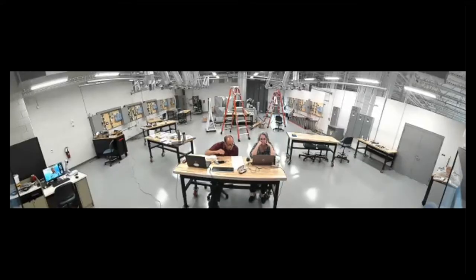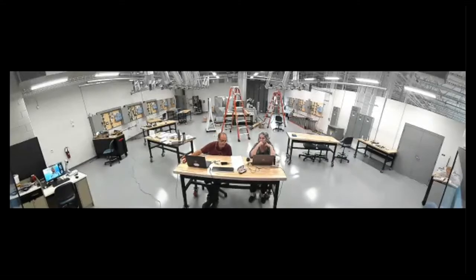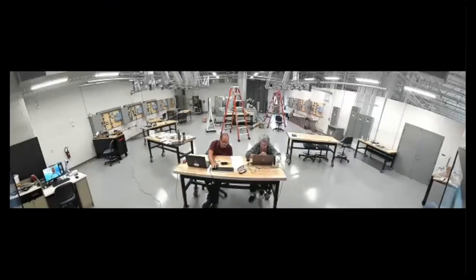Anybody have any questions on that? A little question, I should have asked it yesterday, but in this software, EasyIO, the first thing is following a schedule. Do you want us to just put a tag there? Just drop in a Boolean writable point that you call occupied or OC or however you want to denote it. Okay, we don't want to find the schedule that populates Monday through Friday? No, I don't encourage you to use an actual schedule. That makes your testing very involved and more challenging than it needs to be. Perfect. Thanks.